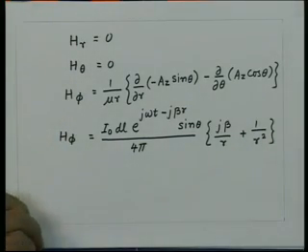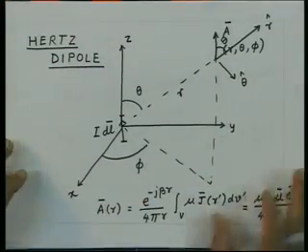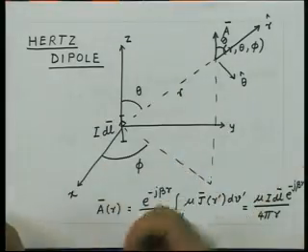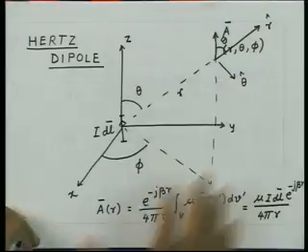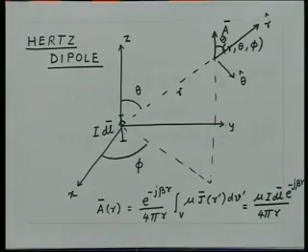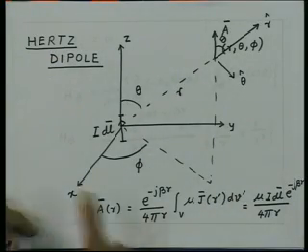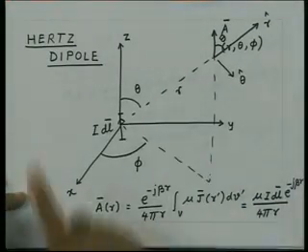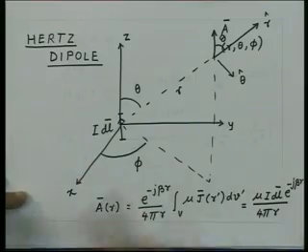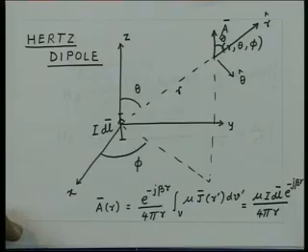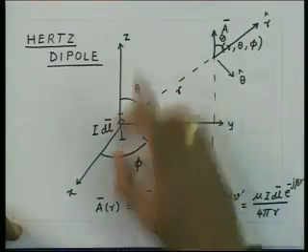So the Hertz dipole essentially generates magnetic fields which are phi oriented. That means the magnetic field essentially goes round this current element. No matter where you go in space, the field will be spiraling around this z axis, because everywhere it has the phi component. As we would have got if this current element was of infinite length, we would get the magnetic field from Ampere's law, which loops around this. The same kind of magnetic field is generated by this current element also.